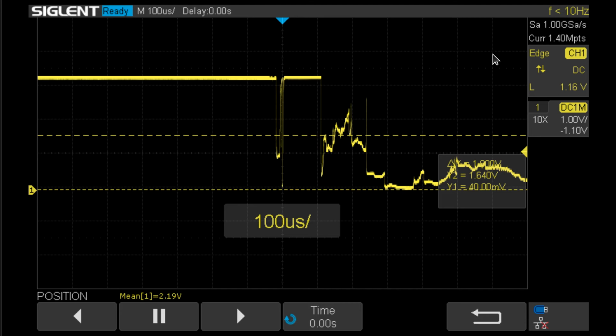Other circuitry that's running at high speed, serial data with bounces. Sometimes you might do this to get rid of, like I said, a single little glitch that might come in on the wire due to some electromagnetic interference or crosstalk or something like that. That could also happen. You do not want a false trigger in that particular situation. This, for example, if this just happened and then nothing, and this is what, 100 microseconds? That's very small. You didn't press it and release it that fast. No human could do it that fast. That would be if it went high and stayed there, and this wasn't over here. That's my point. In that case, you want to use this to actually remove that completely.